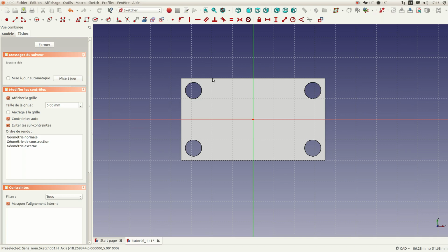So let's go back to our model, and first we have to tell the software that we want to use the previous part. You have the symbol here, and it's a good way to tell the system I want to select this line that is the end of the plane, and I will also select this line. It will help the system link all the geometrical things that we will create relative to the part that already exists. So when you change the dimension of the part, this link will be alive, and it will also drive the modification of the second sketch.